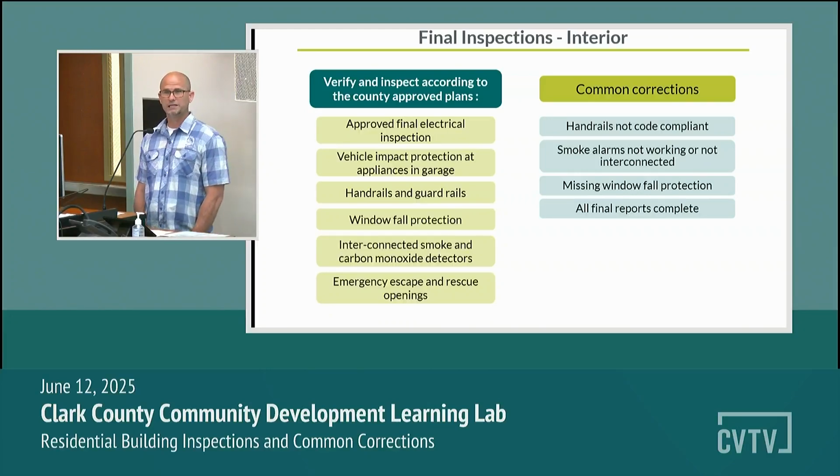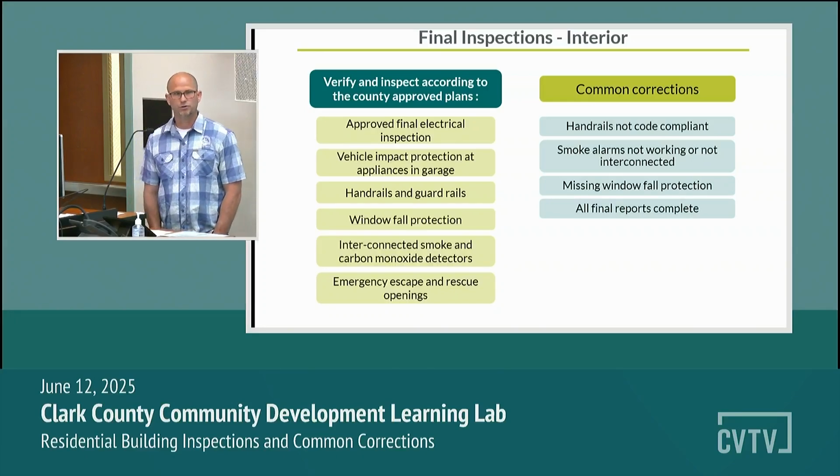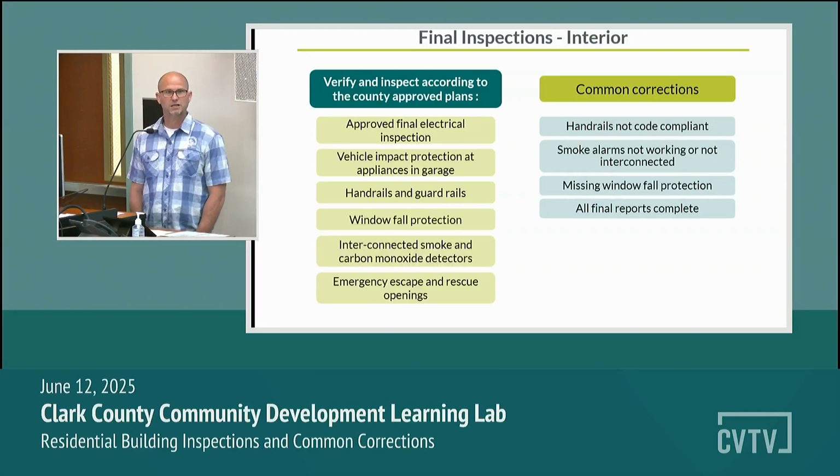Now, a lot of appliances are going to be put in at this time that everything else is done. So in some cases, if you have a water heater in the garage, we're going to verify that you have put an impact protection bollard of some sort in front of the appliance. We don't want you driving into your garage and hitting the gas instead of the brake and ruining your water heater or busting a gas line. So that's something we'll check at final.